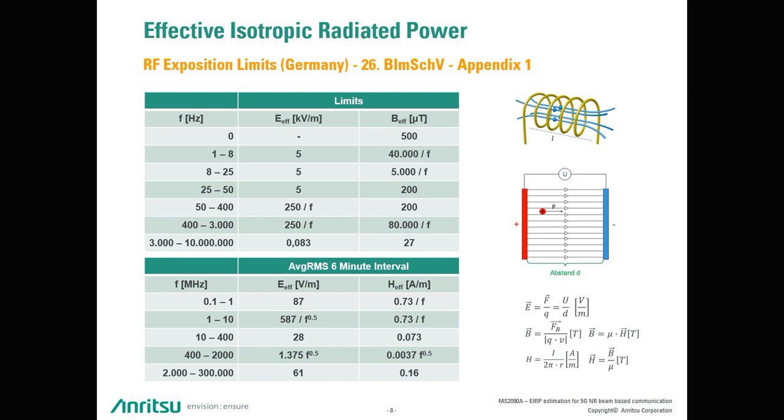The table above shows limit values that are enforced, for example, in Germany, and based on the Ordinance of Electromagnetic Fields. They apply to stationary transmitters with a transmission power of 10 watts EIRP or more, and for systems of lower power in one location with a total power of 10 watts EIRP or more.